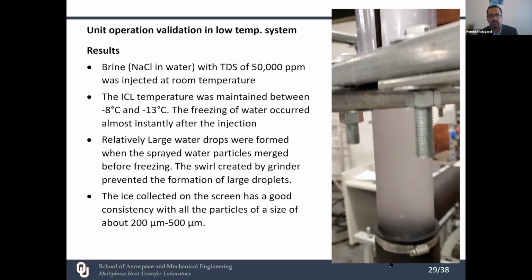At this stage, the water that we recovered, we boiled it, and we measured the mass of the remaining solids. And for this 50,000 ppm, the mass that we collected accounted for a TDS of between 1,000 and 1,500. That's very rough. We just obtained that by boiling the water and measuring the solid mass.